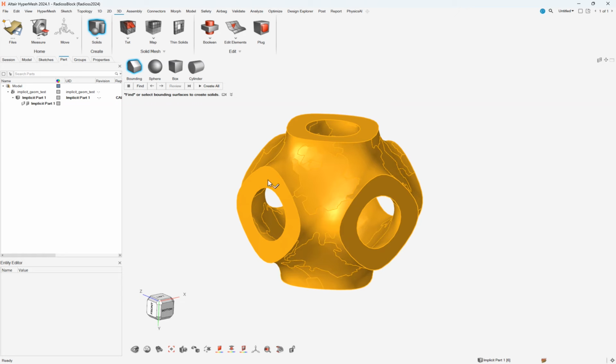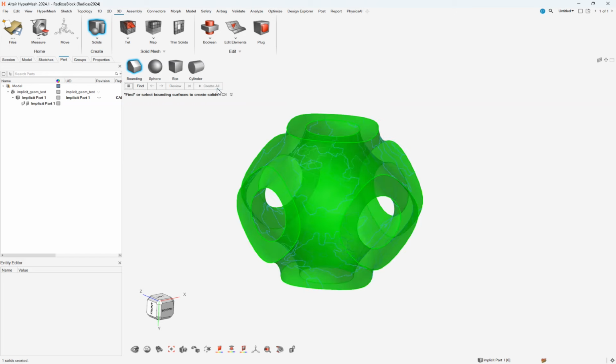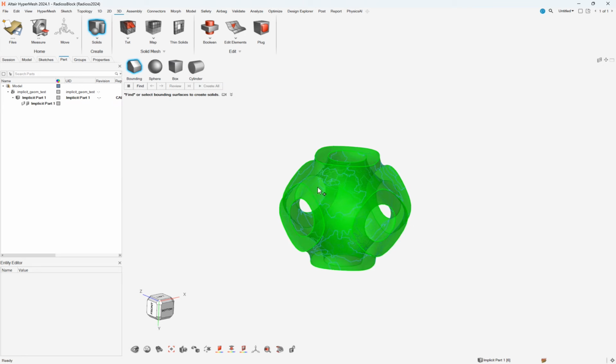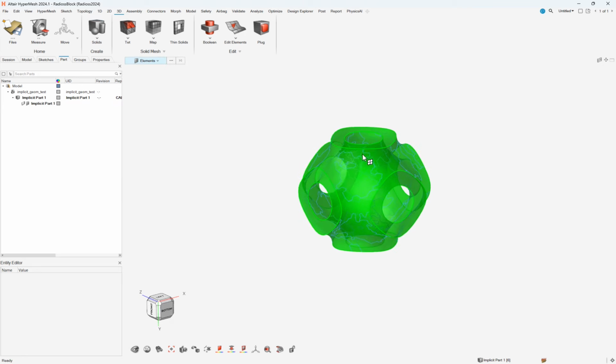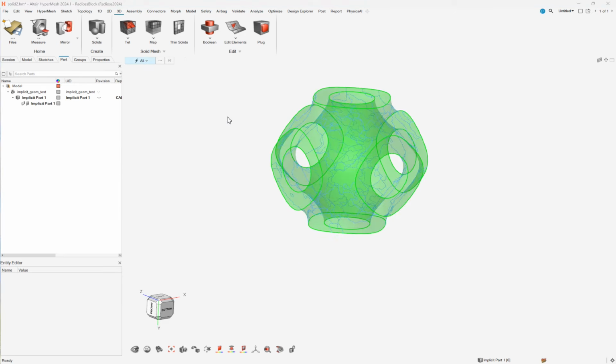So that's the case here. I only clicked on one surface and they all turned orange automatically, which means I can create a solid. They define a closed volume. So I now have recreated a geometry, a solid, based on a surfacic tetra mesh that was imported from Altair Inspire. Now that I've recreated my geometry, the idea is to perform a clean 3D hexamesh onto it.